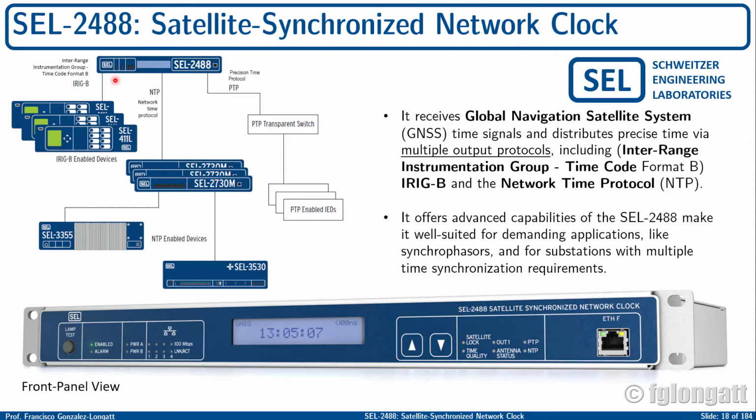As a consequence, the SEL-2488 also allows you to use Network Time Protocol, or NTP. NTP is another of the formats, and it can be used inside the substation for situations where you need this kind of timestamp. And finally, the SEL-2488 also allows communication with another protocol, the Precision Time Protocol, okay?